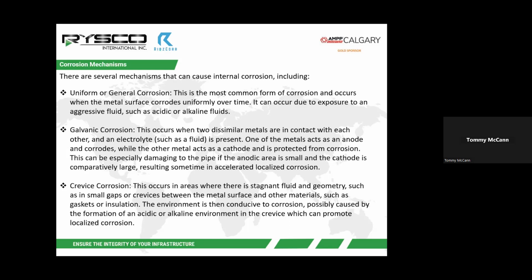Crevice corrosion, not usually an easy one to explain or capture, or even mitigate. Easiest way to think of it is where you have a stagnant environment and the geometry of the environment, like a small gap, or, as the name suggests, a crevice, between a metal surface and another material, which could be a gasket and a flange, or an insulation.